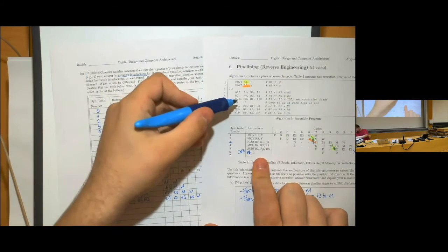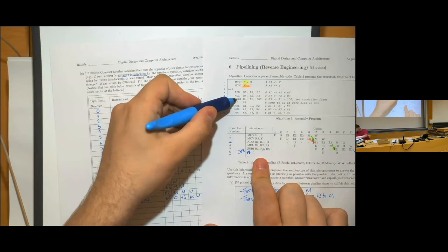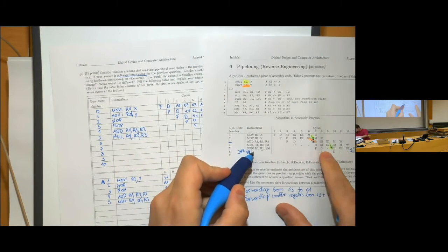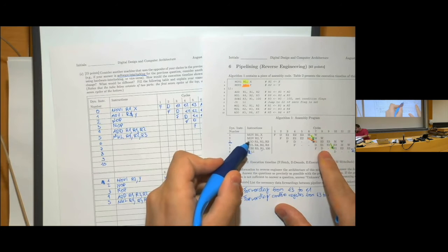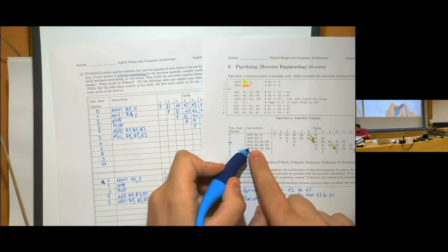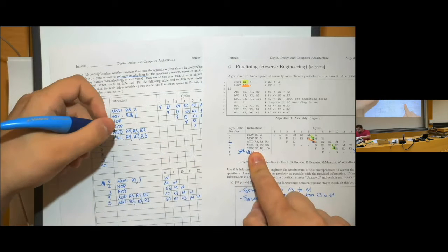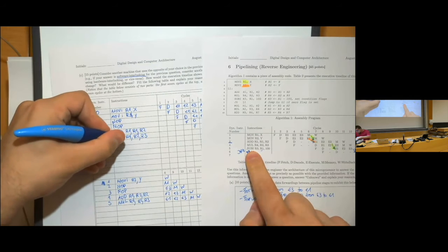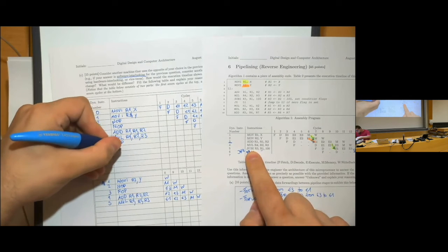And now we have a sub instruction. Let's see, in the hardware interlocking case, there was a stall here because we were waiting for the result from the addition. So we cannot start with the sub directly here. We should have a no-op again, and then we can have sub.